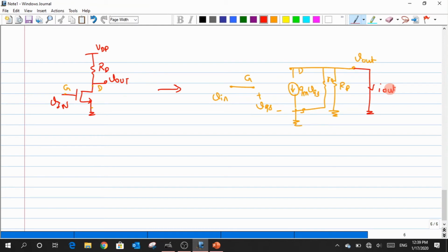Just because the current is flowing in this direction, but we are expecting a current in the opposite direction to flow, it becomes negative. So what about these resistances? Won't the current get diverted in these paths? No, why? The potential at this point and the potential at this point are the same. So whenever you have a resistor with both these voltages VA and VB equal, no current would flow.